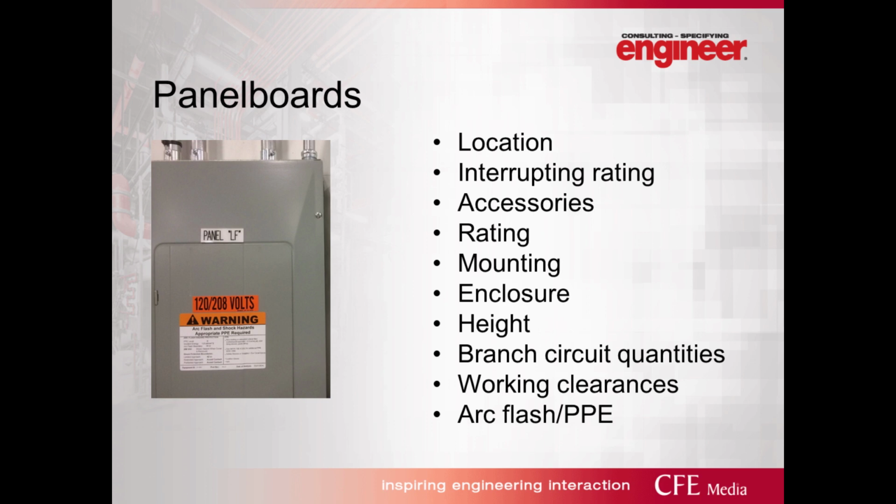Panels also should be rated appropriately to withstand the available fault current. This is required per NFPA 70 section 110.9. The system can be either fully rated or series rated. In a series rated system, each device needs to be rated for the available fault current at its terminals.